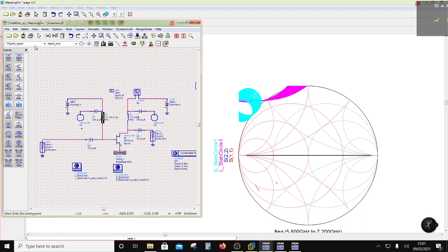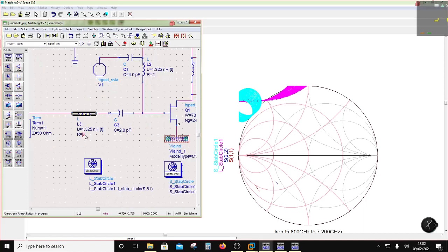I'm going to take the same inductor, rotate it and put it over here. For this value of inductor, 2 ohm is good enough. Roughly, when you do EM simulation on inductors, you will come to know that. Similarly here, roughly 2 ohms. Later on, we will establish this. So this will throw this over here. Let's start with 1 nanohenry.